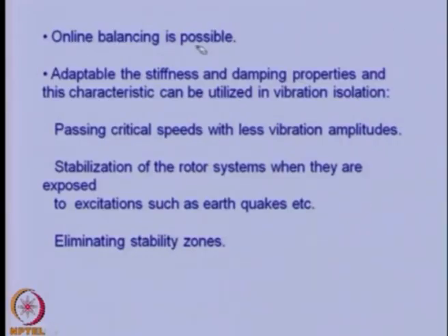With this magnetic bearing, not only can we suppress the resonance, we can also have online balancing, because we can change the stiffness and damping properties online. These are some of the other advantages we can have, like being able to eliminate the instability in the system also.